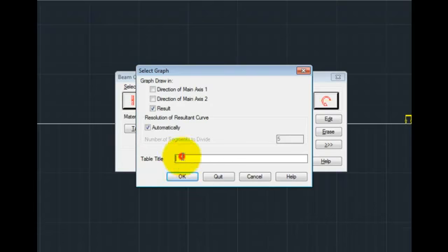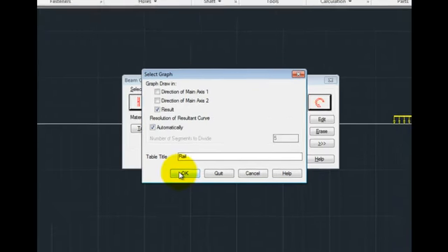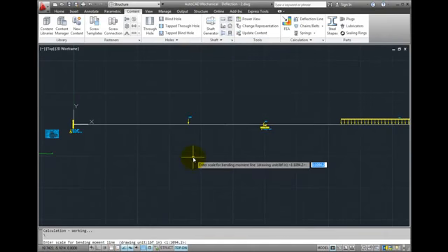I'll enter rail and press OK. Enter the scale for the bending moment line. Right now, Mechanical's suggesting a scale of 1 to 1094.2. Pick a scale here that's going to be easy to measure later. For instance, I might pick a scale of 1 to 1000. And now I'm prompted for a scale for the deflection line. Again, the default scale is an automatically selected scale, but I can override that with something that might be easier to work with, like 5000 to 1.